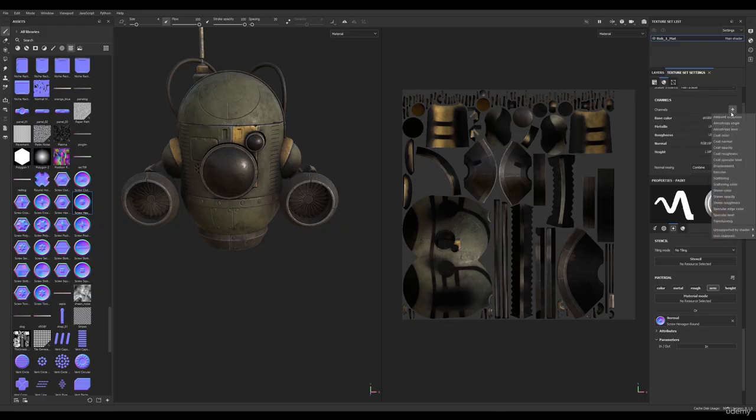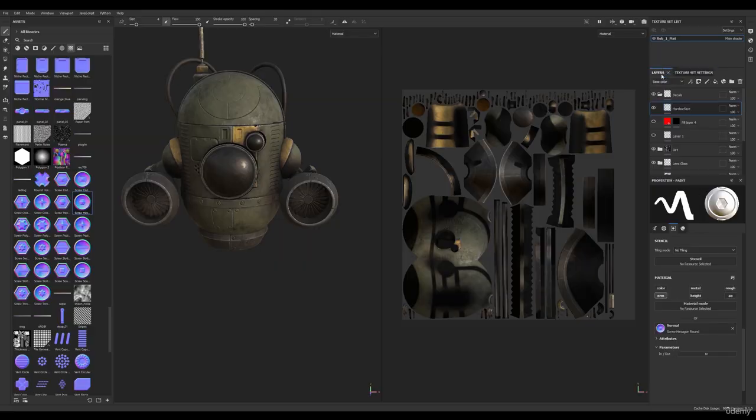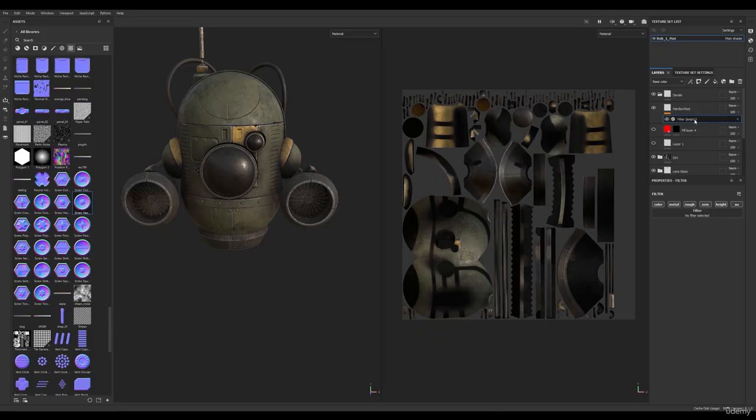So we need to click Add. And the first one is ambient occlusion. So now when we go to our Material Properties tab, we can see we have this ambient occlusion added. But to add more detail to your painted layer, you have to go to Effects and add a filter. And for the filter, we're going to use a filter called Height Blend Ambient Occlusion.